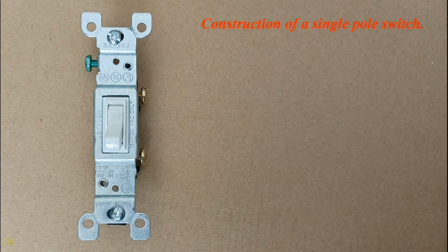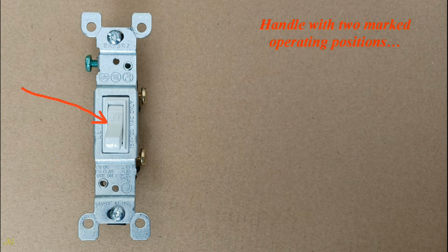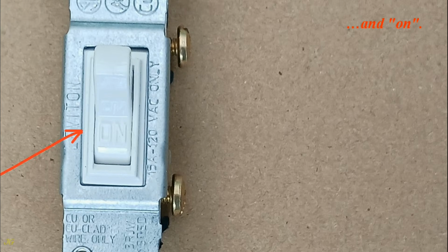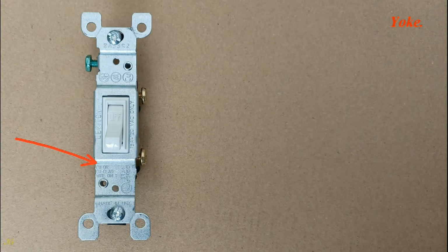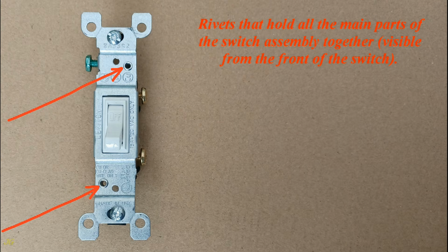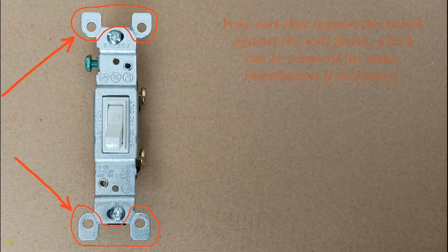Construction of a single pole switch. Front view of a single pole switch. Handle with two marked operating positions: off and on. Yoke. Ground screw attached to the metal yoke. Rivets that hold all the main parts of the switch assembly together, visible from the front of the switch. Yoke ears that support the switch against the wall finish, which can be removed for some installations if necessary.